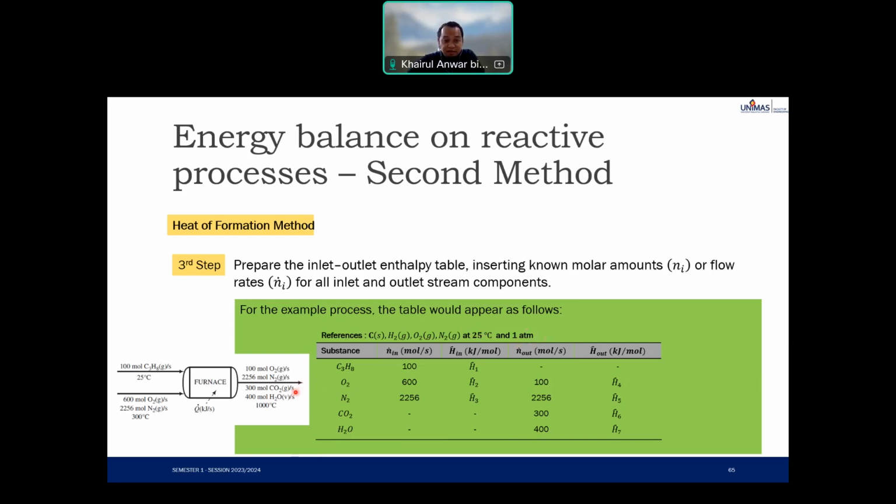All right, for this case, propane, because the reference doesn't have propane, because it's a species, heat of formation now. Since there is no propane as the reference, propane cannot be zero now. Although it appears here, its inlet condition is 25 degrees C, 1 atm, but it cannot be the reference point. So in this case, you have 7 enthalpies you need to determine. If you see the heat of reaction, only 6.